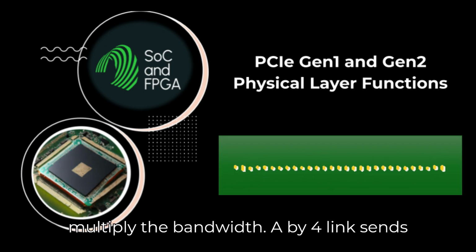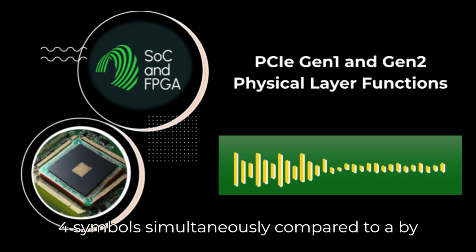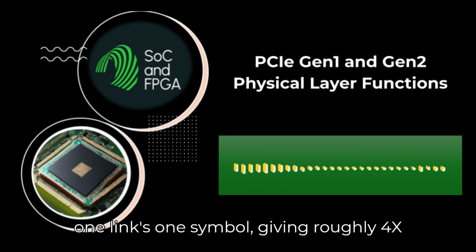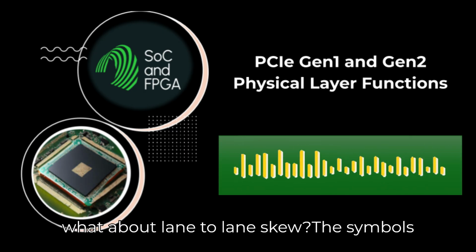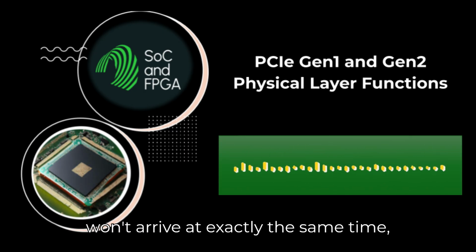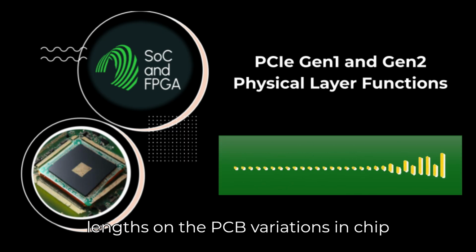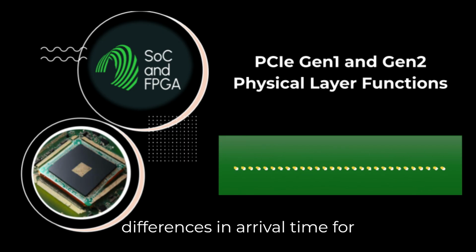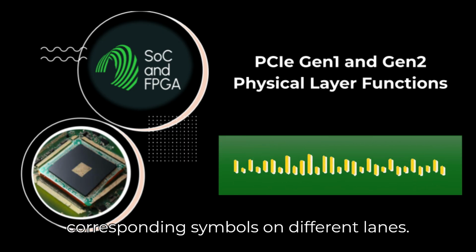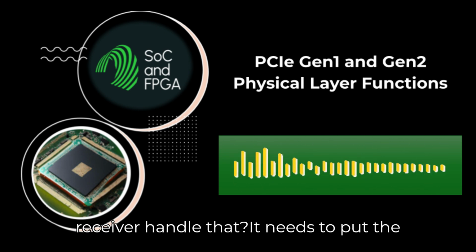The goal is simple. Multiply the bandwidth. A by-4 link sends 4 symbols simultaneously compared to a by-1 link's 1 symbol, giving roughly 4x the throughput. Seems simple enough. But what about lane-to-lane skew? The symbols won't arrive at exactly the same time, right? Correct. Tiny differences in trace lengths on the PCB, variations in chip circuitry. It all adds up to slight differences in arrival time for corresponding symbols on different lanes. That's lane-to-lane skew.